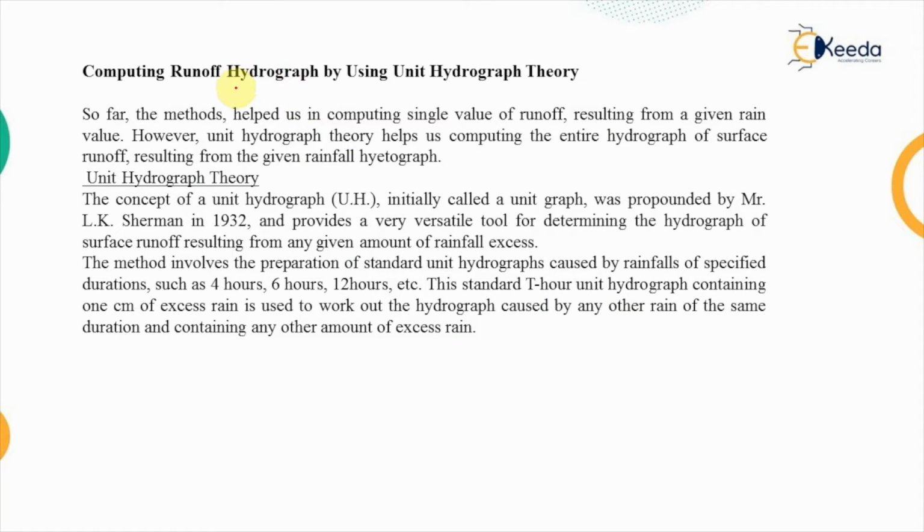So we were doing the computation for calculation of the runoff value. If we want to compute the runoff, we have looked at one of the methods, that is known as the hydrograph, which is a plot of the discharge versus time. Now, this can also be done by using the unit hydrograph theory.